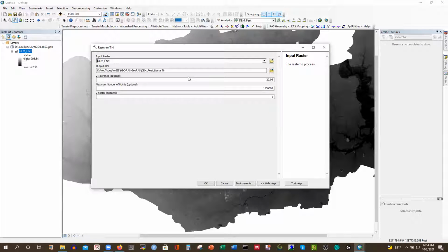So the main tip for this GIS software package is whenever you do something new, you should create one separate folder and create one geodatabase, and then you can do everything there. Then you'll have access in future, and you can even send it to any other person. They will even be able to do the same thing.